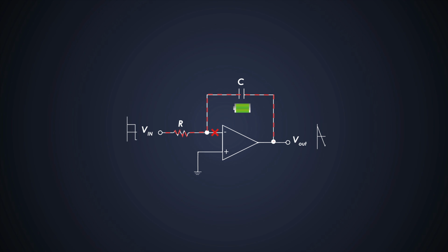As the capacitor is connected to the virtual ground, the voltage across the capacitor is the output voltage of the op-amp. During negative half cycle of the square wave input, the current is reversed. The capacitor is now linearly charged and produces a positive going ramp output.